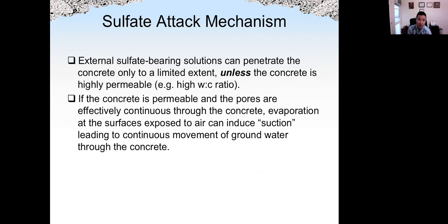So sulfate-bearing solution from outside of concrete can penetrate into the concrete only to a limited extent, unless the concrete is very permeable, for example, the water-cement ratio is very high.